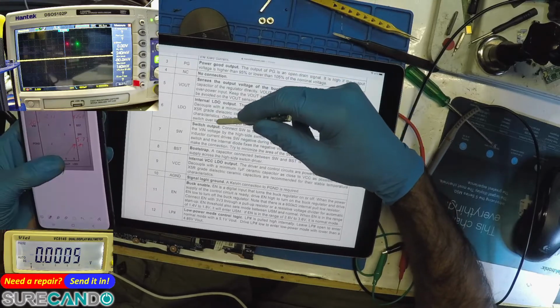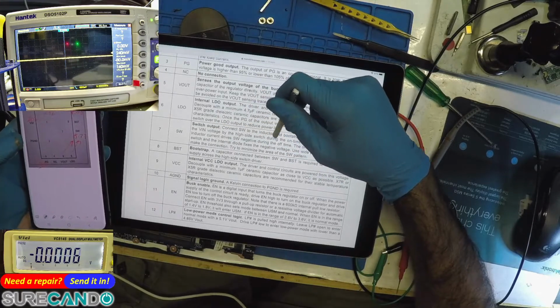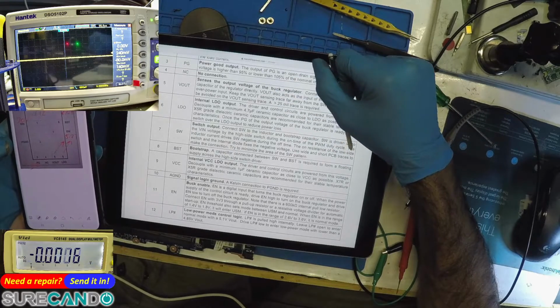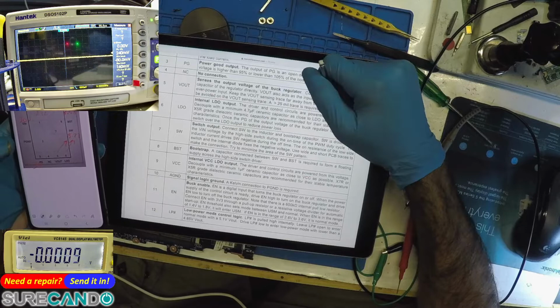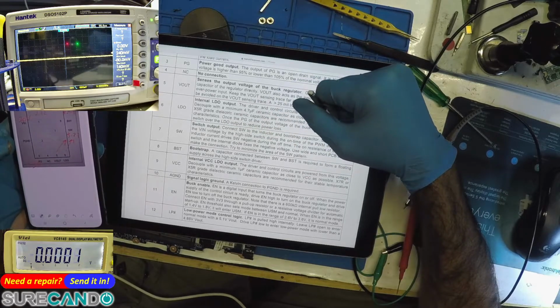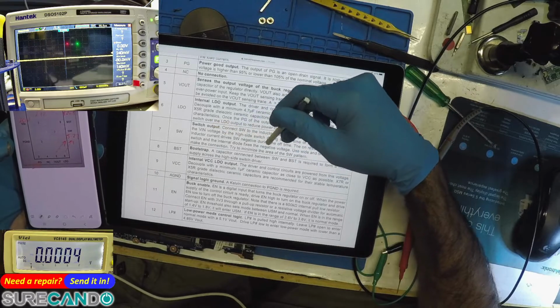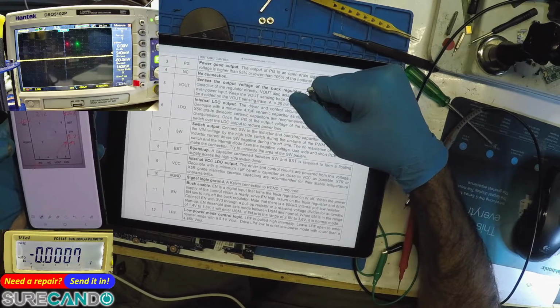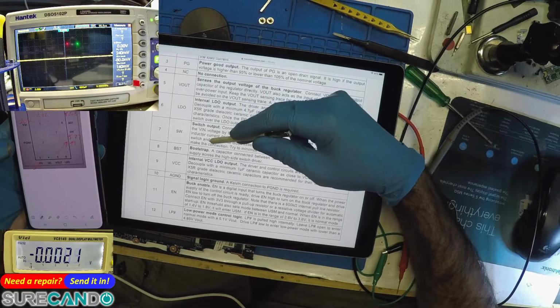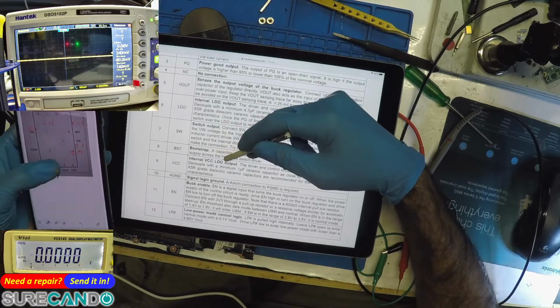Switch output. Okay. Connect the switch to the inductor or bootstrap capacitor. As switch output is driven up to the VIN voltage by the high side switch during the on time of the PWM cycle. Okay. BST. What's BST? Bootstrap.